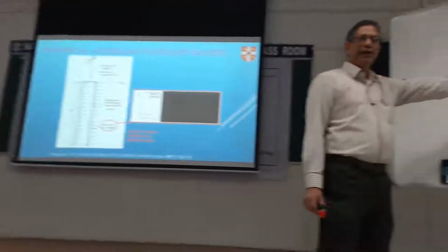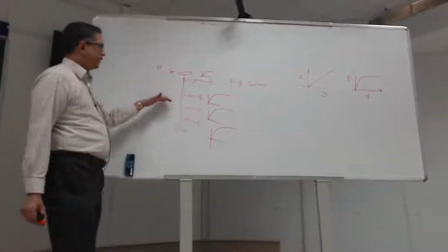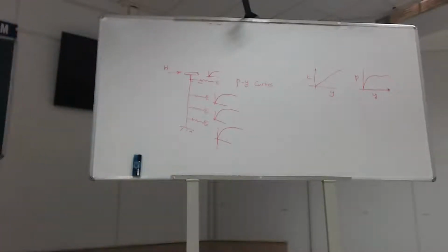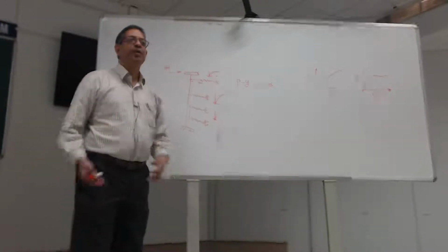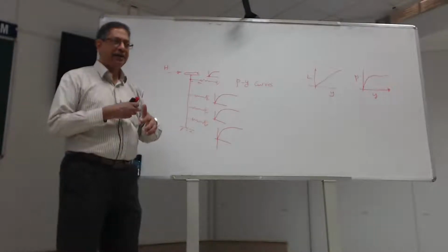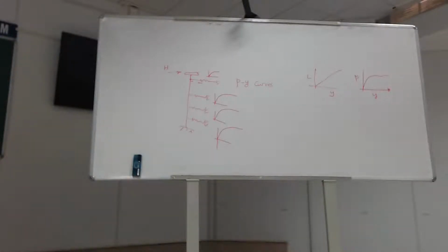Having a nonlinear spring gives you the complexity you need when you're handling soil. And for various reasons, as I said over the past few days, that's the critical bit. You need to get that right. And we can include the depth effect by making these curves bigger and bigger as they go deeper. So we can allow for the increased stiffness at high confining pressure. And we can also include this reaching of the plateau, which basically means you are including some kind of plasticity, or limiting pressure, at large displacement. There's another bit to do with cyclic loading, which I'm not going to cover now, but we'll come back to that later. If I forget, do ask.